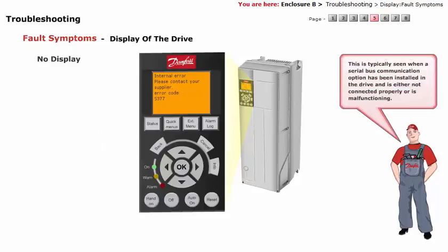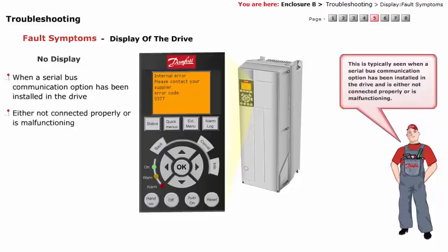This is typically seen when a serial bus communication option has been installed in the drive and is either not connected properly or is malfunctioning. If neither indication is available, then the source of the problem may be elsewhere.